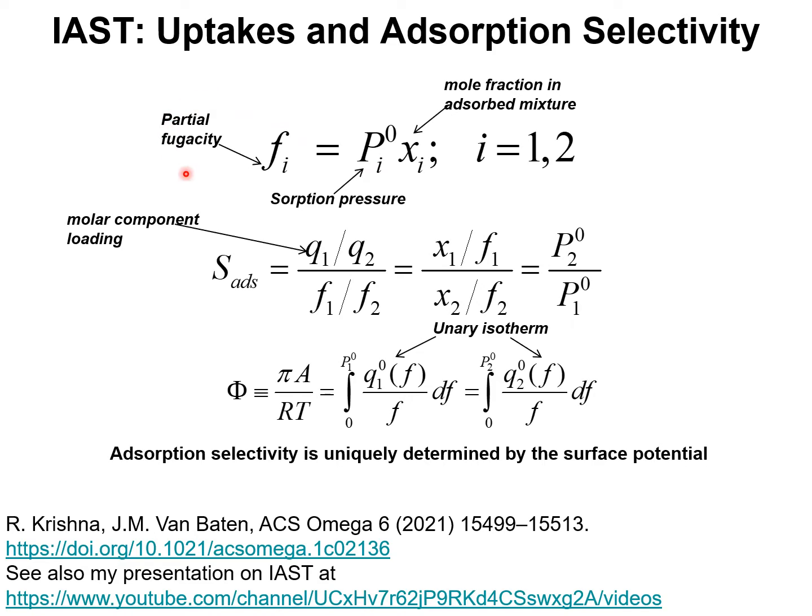The partial fugacity of component i in the bulk gas mixture is equated with a term which is the sorption pressure of component i times the mole fraction of that component in the adsorbed mixture.